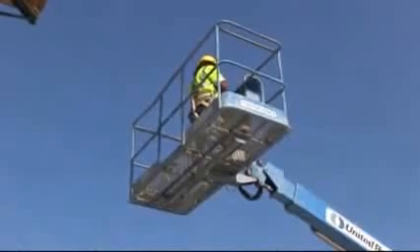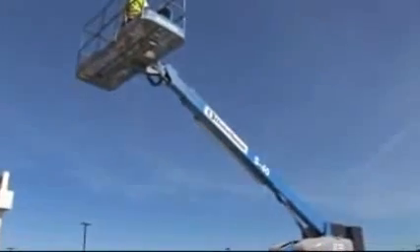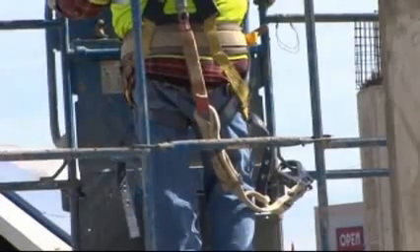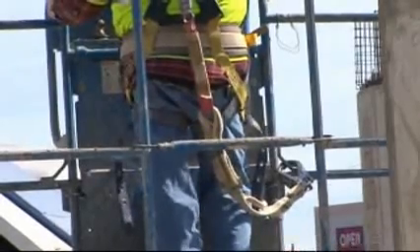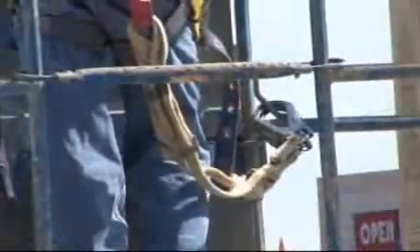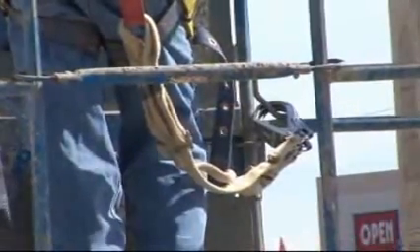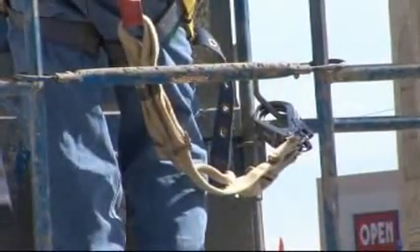Guardrails and buckets provide some fall protection, but due to the catapulting characteristic of lifts, it is necessary to have additional fall protection. A full body harness should be worn and a lanyard attached to the boom or basket when working from an aerial lift. The length of the lanyard must conform to the lift manufacturer's guidelines.